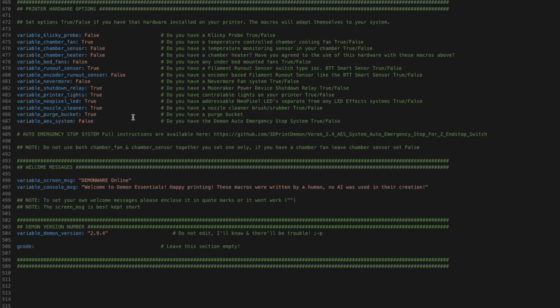So if it hit the heat block, it will try printing with the heat block at 0 instead of the tip of the nozzle, and that's serious print damage. That's trashing your bed. That's trashing your nozzle, your heat block, your hot end probably. And not only that, it will be putting a whole load of force and strain on your linear rails and the gantry system of your printer. So it's basically a printer saving device.